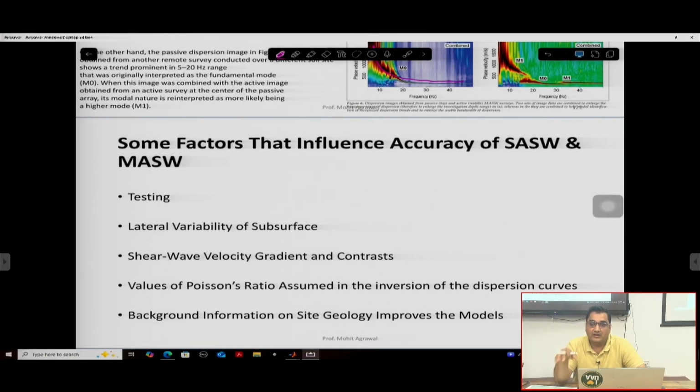You will also find many papers that talk about using the HVSR technique and MASW techniques together. That means you use the HVSR curve and the dispersion curves together. When we were talking about finding the address in Delhi, we were giving more and more information in order to constrain our search area to the Delhi region.